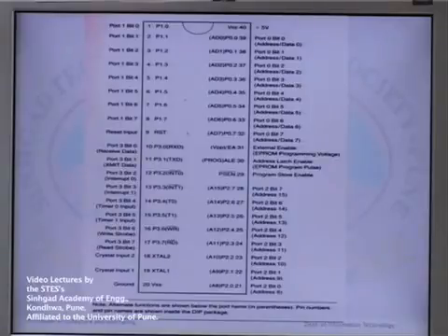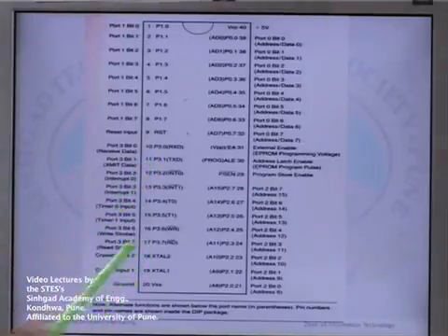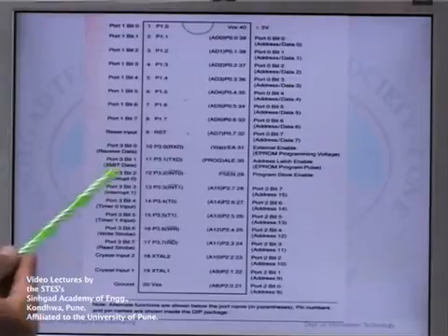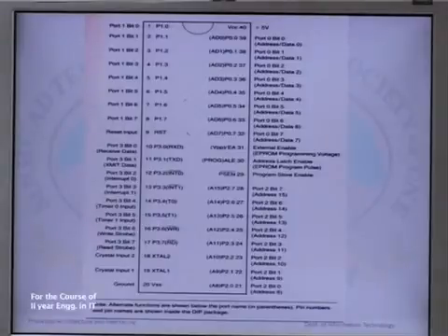Pin number 10 to 17, as shown here, are nothing but the port 3 pins. Similar to port 1, each of these pins can serve as general input or output. Besides, all of them have alternative functions. Pin number 10 is RxD, serial asynchronous communication input or serial synchronous communication output can be provided on this pin.